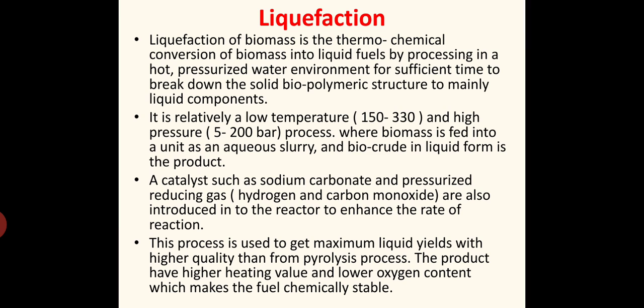This process is used to get maximum liquid yields with higher quality than from the pyrolysis process. I have already told that during the pyrolysis process we also obtain some liquid fuels, but complete conversion is not practically possible, so in order to get the maximum liquid out of the process, we go for liquefaction. The product has a higher heating value and lower oxygen content, which makes the fuel chemically stable.